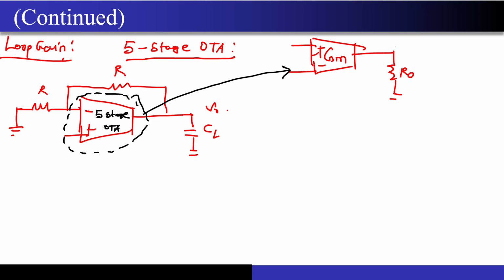Now why have I not taken the output capacitors over here? Because remember, this is the biggest one here, okay? This is 10 picofarad. This is a very huge capacitor. Whatever femtofarad level capacitance, even if I get around 600 or 800 femtofarad at the output, this 10 picofarad is much larger. So it does not make any sense to consider the parasitic capacitance over here. Correct? The simulator will do its job. Our job is to do a first cut hand calculation and to get the guiding design equations so that if our result does not come accurately in the simulator, we know what parameter to change while doing the design of the circuit. Correct? So now I will be replacing this.